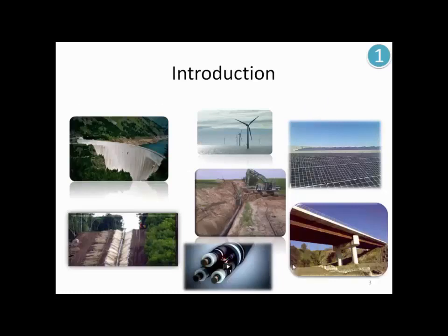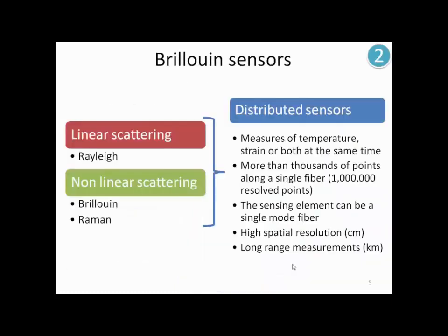Nowadays, structural health monitoring has converted in a wide working area due to the requirements in terms of safety and security. So we have to develop some sensors to try to avoid or to detect cracks on dams or on bridges. Also detect leakage on pipelines. So we need to develop some sensors, like optical distributed sensors. With this kind of sensor, we can measure temperature, strain, or both at the same time, always depending on the